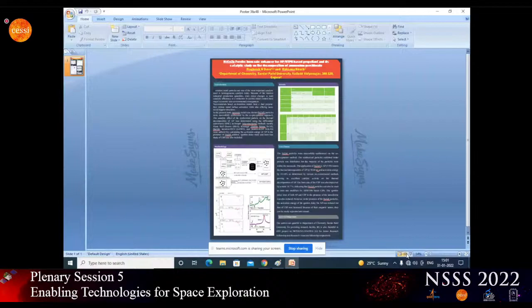We utilized metal nitrate salt and sodium hydroxide as a precipitating agent, by which nickel zinc ferrite (NiZnFe2O4) particles were successfully synthesized using the co-precipitation method. And the effect of 1% nickel zinc ferrite additive on the thermal decomposition of AP and the burn rate of AP-based composite solid propellant was investigated.